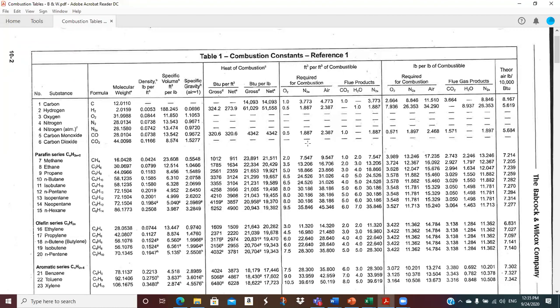And you know how much excess air because you have that stack loss calculator, right? That's in the measure tool. You put in oxygen, and it'll tell you excess air. It depends which oxygen level you're going to run. If you're going to run 8.1%, I bet that's at least 50% excess air. I'd have to check.